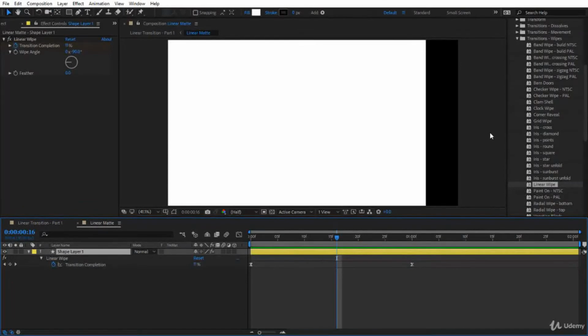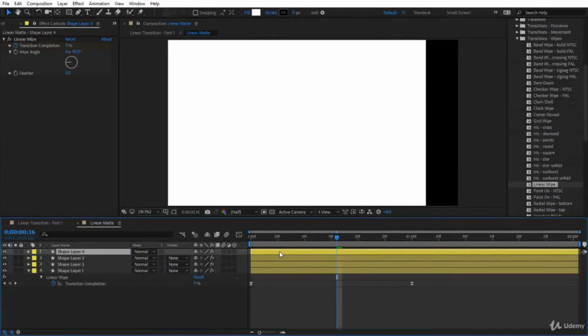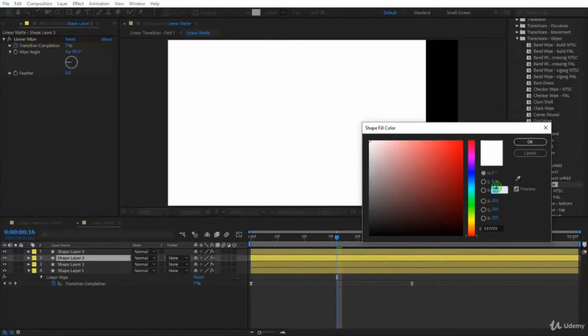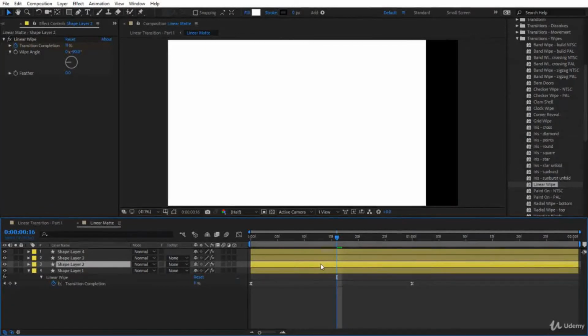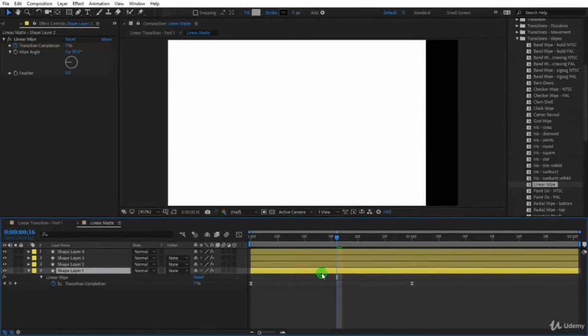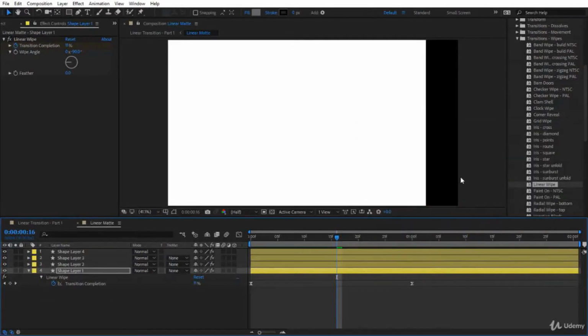We're going to do almost the same process here. Of course, we duplicate 3-4 times, as many as you want. Now you want to change the colors. So the first one is going to be white, 100%. Second one, let's make it 80% white. You notice the 80% white just makes it a bit darker. So the nearer you get to plain white, the more percentage of black you have. I'll check the other one and make it 60%, and the last one, let's make it 40%. Okay, you can add another one and make it 20% or so.